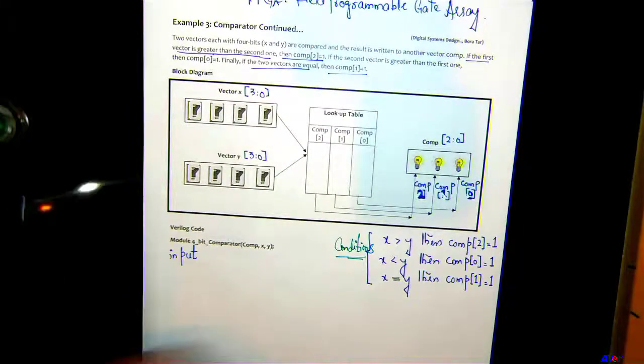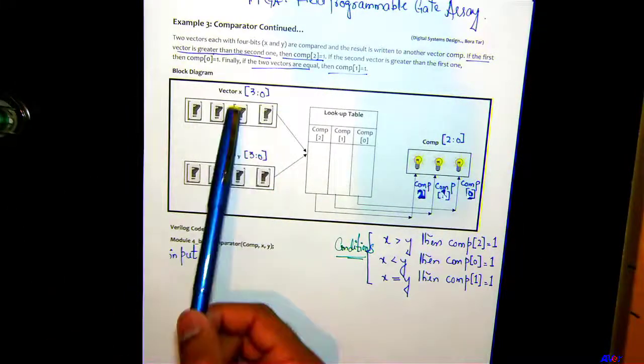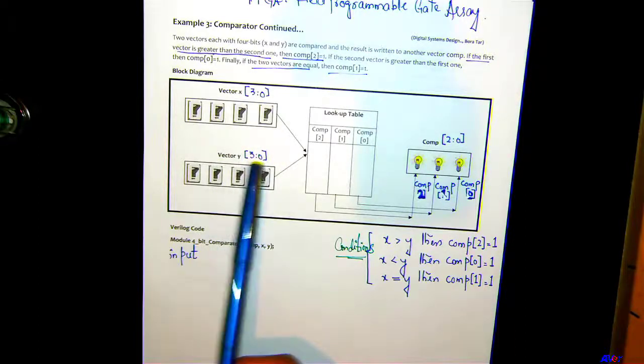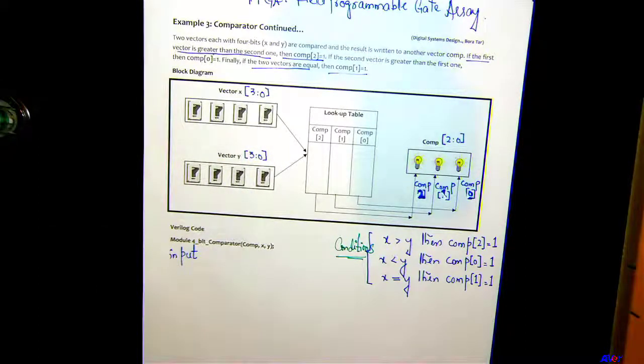When we are actually designing our logic circuit, what FPGA thinks is, if you have 3 inputs, there could be 8 possible combinations, 0 to 7, and for each combination this is the output. So it only looks at that output which is in this lookup table right here. Okay, so we have 4 bits here in vector X, and 4 bits in Y. In the previous example we only had one bit each, x and y, so we had four combinations: 00, 01, 10 and 11. Here, with 8 bits, the combinations are going to be from 0 to 255, right? It is easier for us to wire those combinations in the FPGA, and the FPGA would just memorize for each combination what is going to be the output, and that is what we know as a lookup table.